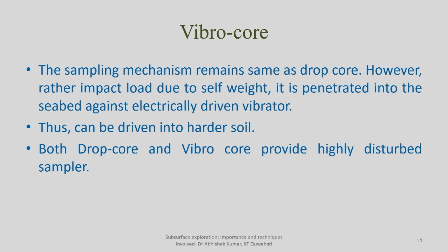The other one is vibro core, which is very much similar to the previous one, that is drop core. The only difference is that in drop core you are pushing the sampler into the soil under the impact load because of the self weight of the pipe. In this particular case, you are pushing it into the soil by means of some kind of electrically driven vibration. So, you are lowering the sampler or the tube into the sea by means of electrically operated vibrations, as a result of which it will penetrate into the seabed, and then you can bring it onto the surface for necessary investigation.